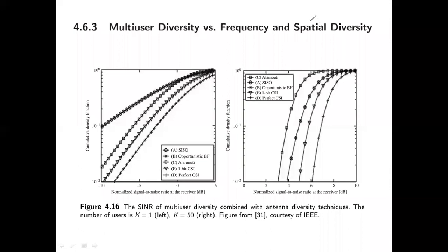So the spatial diversity, once again, let me tell you. One transmit antenna and one receive antenna. If there is a single channel and the channel is very poor, then because of poor channel feedback, I will settle for 16 QAM with rate half code, which is of very poor throughput.